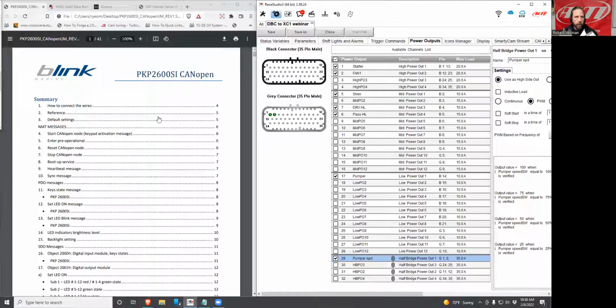Yes, and you run into 10 or 15 requests, and we're sending them sequentially. So as soon as one's done, the next one gets sent, and that's on the millisecond period. And some ECUs can buffer all of this information and hold it until they can have a chance to respond, and other ECUs cannot. The appropriate way would be to set a respected timing so that you're waiting for a response back before your next message is sent, and you just don't have those tools yet.